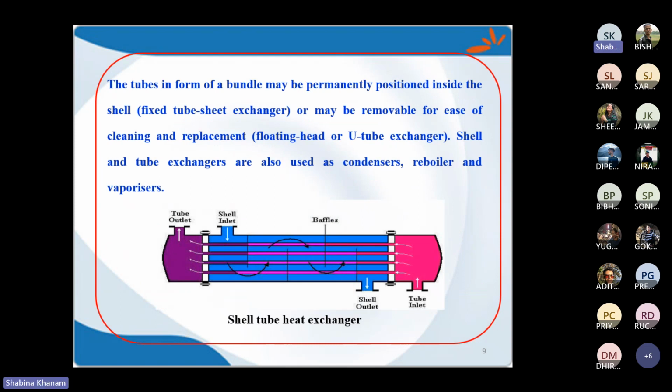Now, this is the tube sheet, and these tube sheets are used to insert the tubes, or we can say hold the tubes. So the tube will be inserted over here, and in between it will remain hanging, right? So when we consider this tube sheet, the primary purpose is to hold the tube, because the tube will be inserted in this. The second purpose is that it separates the fluid of the shell side and tube side.